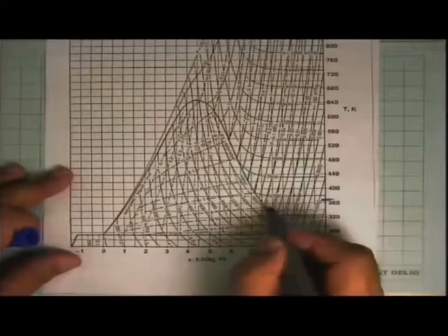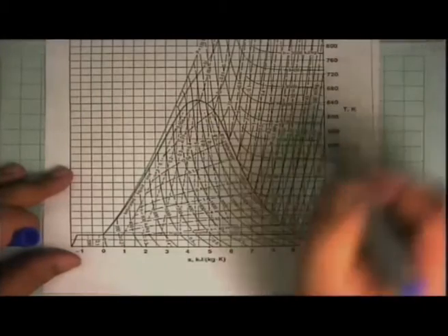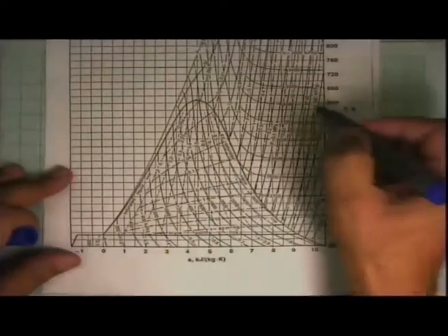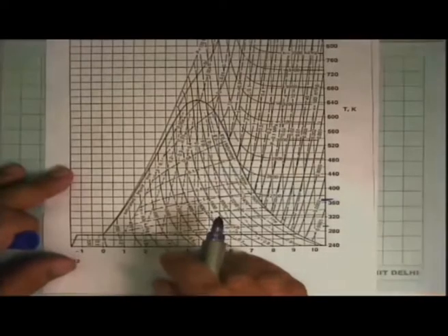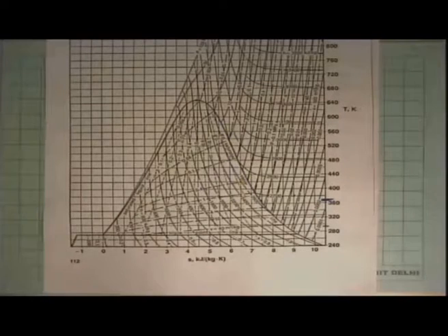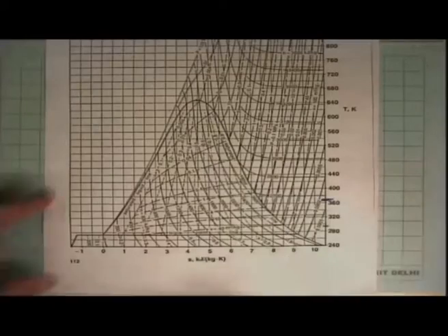The trouble is that if you look at 360 and you start looking at the numbers that come out, you'll see here that the specific volume is on the order of 100 meter cube per kg. So this is a very, very big specific volume. This is vapor at low pressure. It occupies a very large volume. So to get the same mass flow rate, we need very, very big pipes, many meters in diameter, before we can even make this thing work.